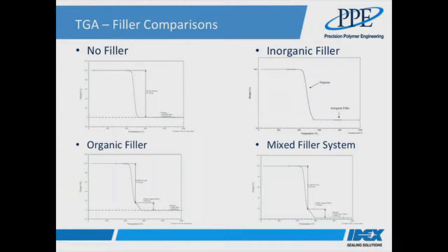The changes in profile with temperature is what we're really interested in. So if we take a closer look at the examples, the first one, top left, is fairly straightforward. It shows a smooth profile of weight against temperature and drops to 0 at around 500 C or 932 Fahrenheit. If we look at the spectrum top right, it shows a similar profile but doesn't drop to 0. There's a residual mass even after the ambient changes all the way up to 1000 degrees C, 1832 Fahrenheit, indicating an inorganic residue or inorganic filler in the compound.